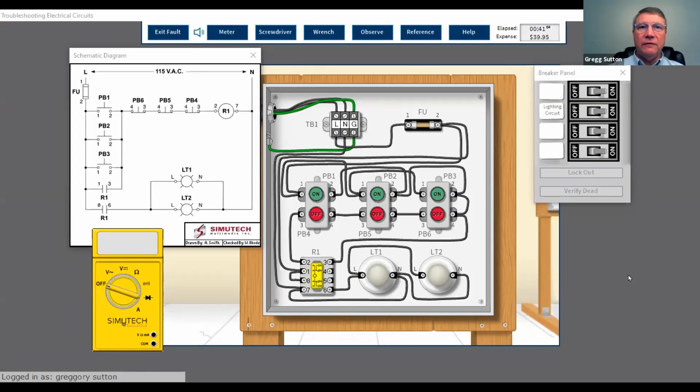Sure. Some of them might be 220 volts, for example, where you have 2 hots. Think of your house, right? You've got a dryer in your house. If it's electric, that probably has 2 hots to it. The best example is probably an electrical water heater. There's no neutral to that. It's 2 hots so you have 220 volts. Another one might be DC, where you have positive and negative.